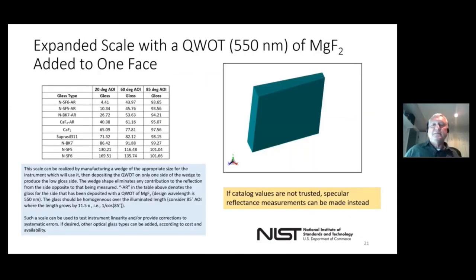So to achieve this, since there are two surfaces to a transparent wedge of glass, why not deposit a simple single layer anti-reflection coating on one surface? For example, consider a quarter wave optical thickness, some people call that a quat, of magnesium fluoride on one surface. Magnesium fluoride is widely used in the coating industry, and given this simple coating deposited on one side of the wedge, Zemax computes the reflectance, and from that, the corresponding gloss, which you see here.